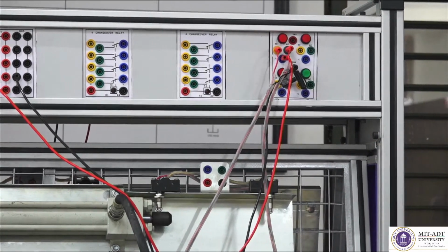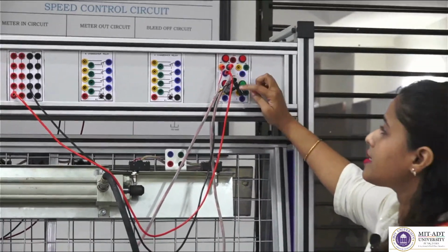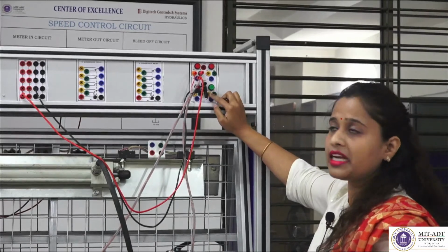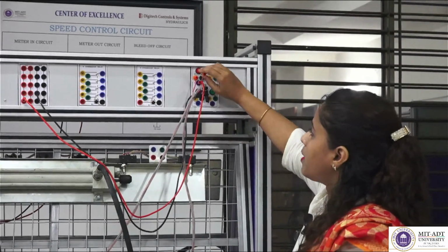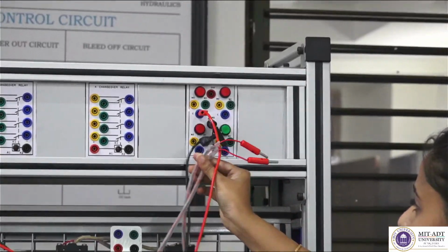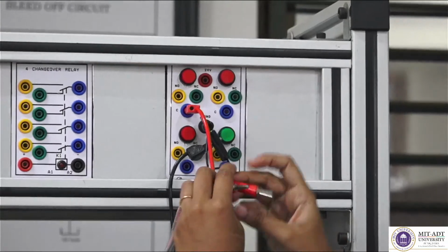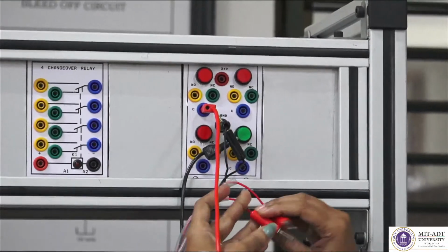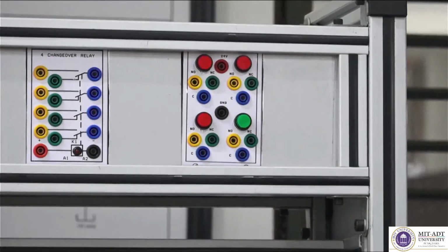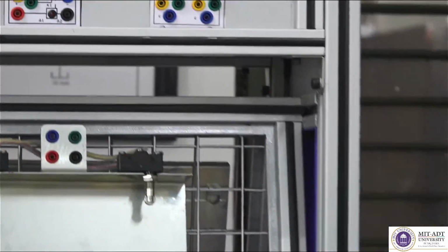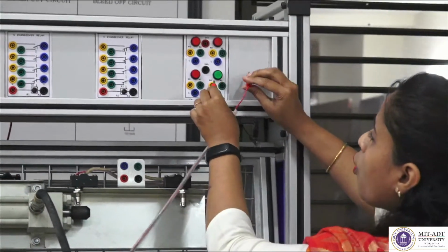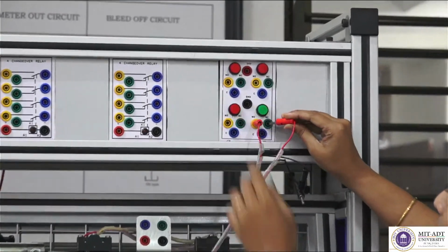Now I am not going to move all these grounds. I need to put each and every connection below this green color button. So I am just removing both red color wires of both the solenoids. I will show it again: both red color wires of both the solenoids will go into NO and NC.